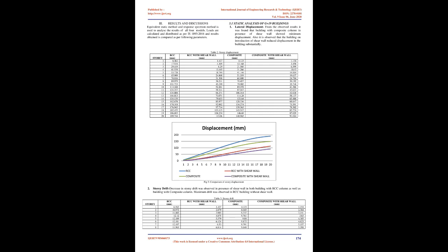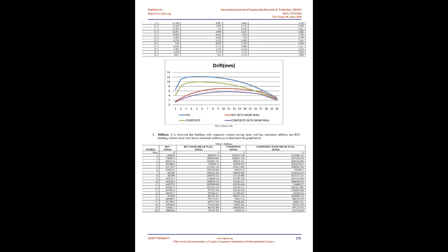However, with the growth of population there is increasing growth in high-rise buildings in metropolis. It is observed that the use of composite members over RCC members is much more effective and economical in high-rise buildings. When a steel component like I-beam is attached to a concrete component like floor slab or bridge deck, a composite member is formed. In composite structures, the high strength of the concrete in compression and high strength of the steel in tension are utilized in combination.